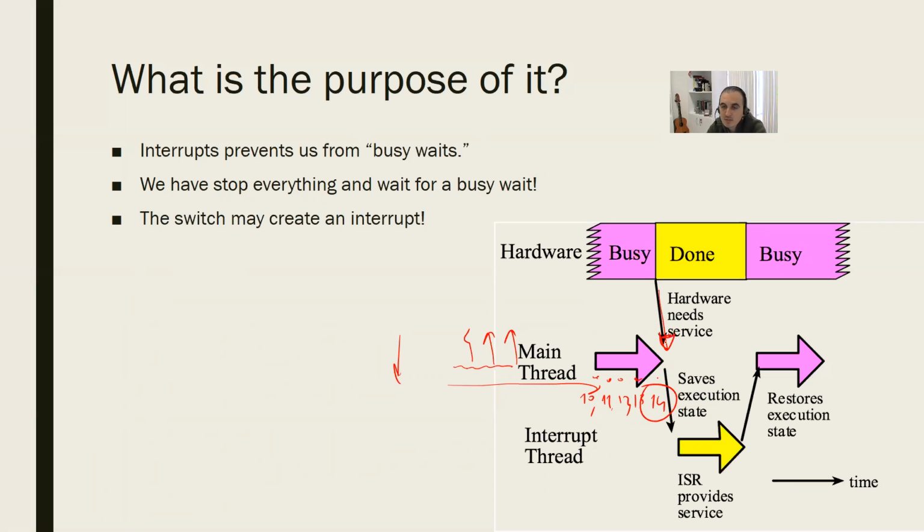The interrupt comes. Your main code is frozen, okay? Frozen. You don't lose or forget anything about it. You jump to another subroutine. You run that subroutine, you do the job. When you're finished, you come back and you continue from line 14, line 15, line 16, line 17. So it is like going and coming back. So it is like a subroutine jump. You know what a subroutine jump is?